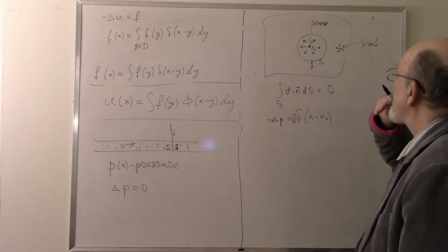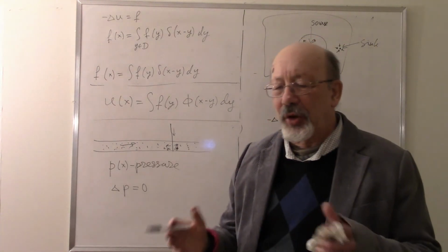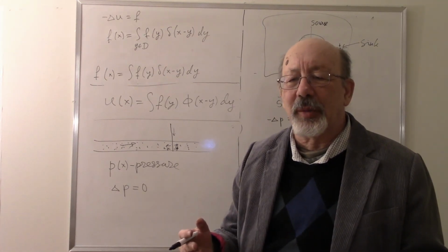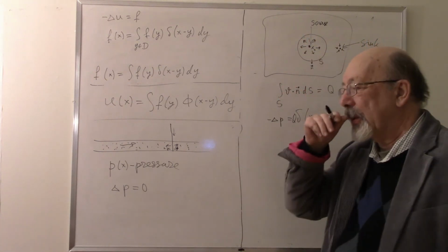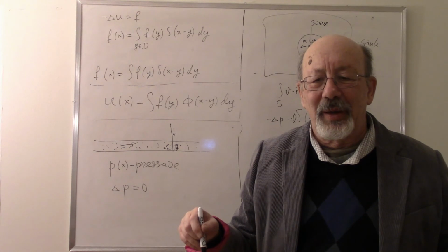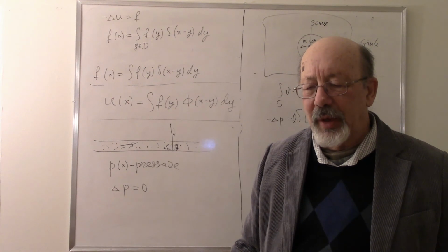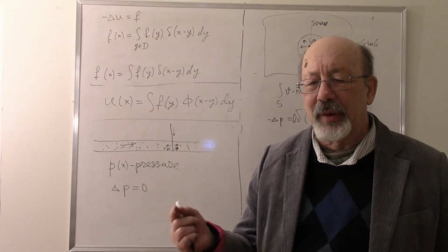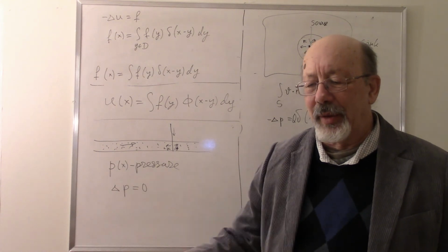And if you have both source and sink, the pressure and the flow will be a sum of the partial terms due to just one source alone and sink alone. Now, if you have some number of sources and sinks throughout this layer, then the pressure is the sum of the pressures produced by each well.